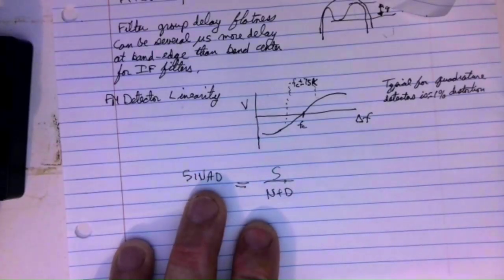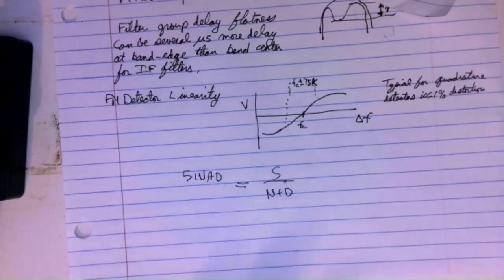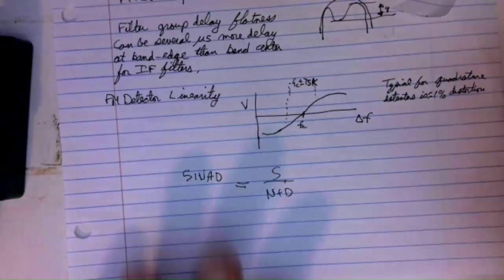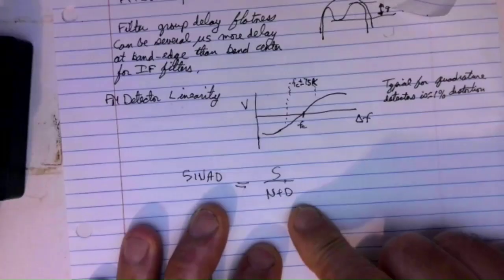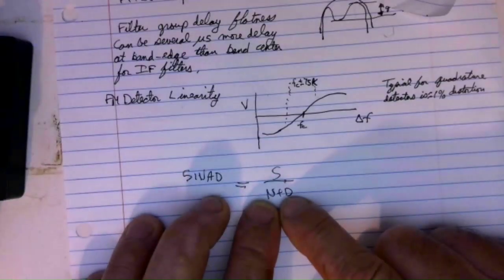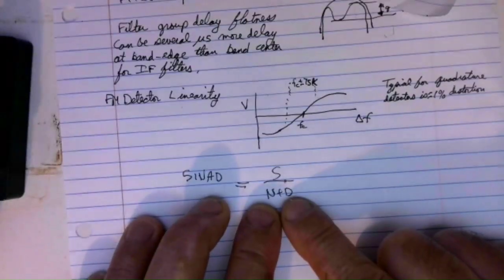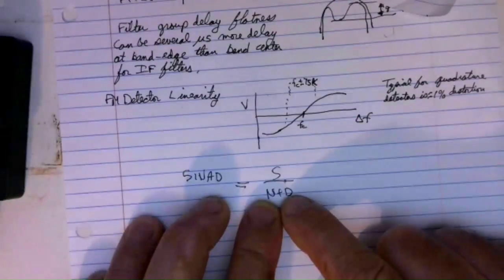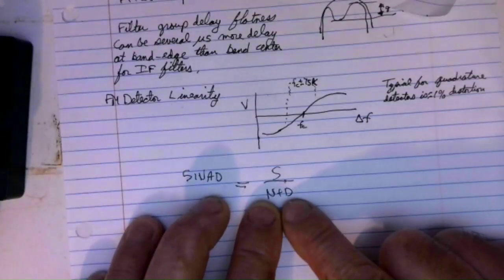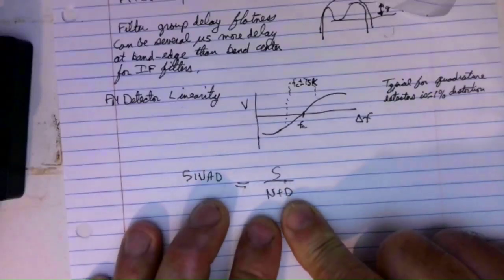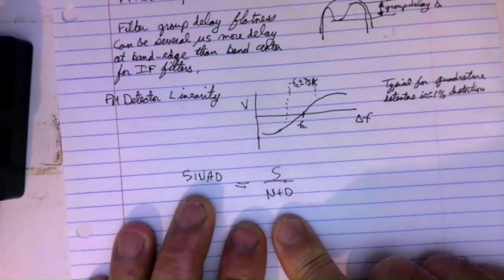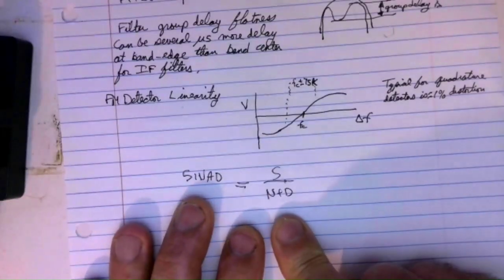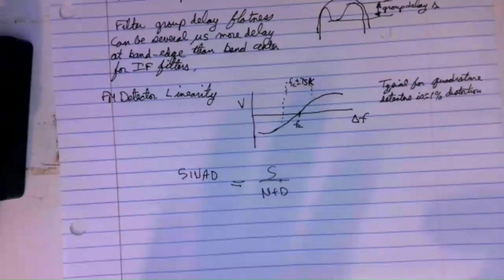Okay. Now, for our little sensitivity example, we used 40 dB SNR, and we weren't rolling the distortion into the sensitivity measurement. Obviously, if your distortion is bad enough, just like hum and noise, it would matter, but we're presuming if you're looking for 40 dB SNR, that your distortion is good enough so that it doesn't limit that. But I think that's enough said on distortion.